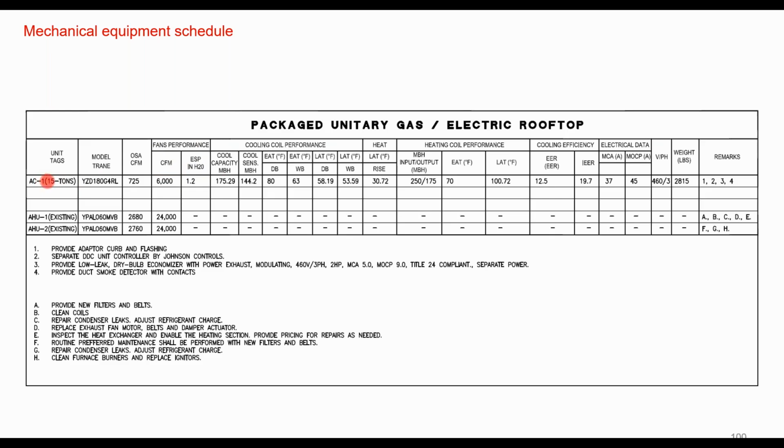So what you might have to end up doing is go look up this model, right? Or you might have to ask them for the selection sheet for the specific piece of equipment. So it's not as simple as just going to the schedule and picking it up. A lot of engineers will have the fan power on here, and they likely will have a brake horsepower, which is what you need for the model, right? Instead of the full load on the motor.